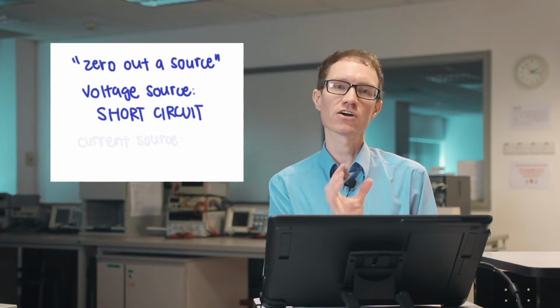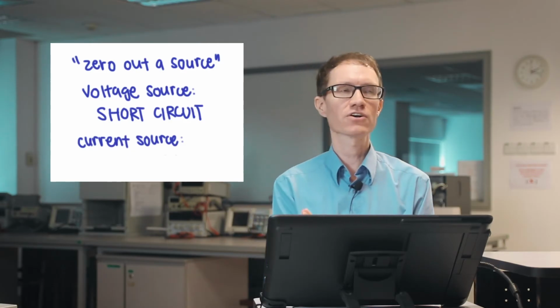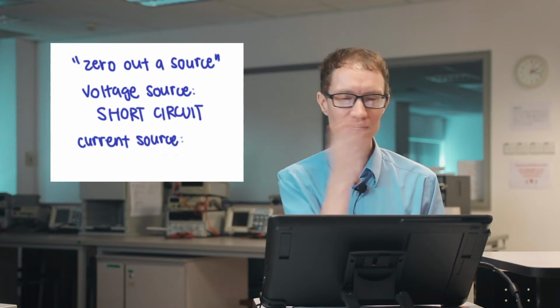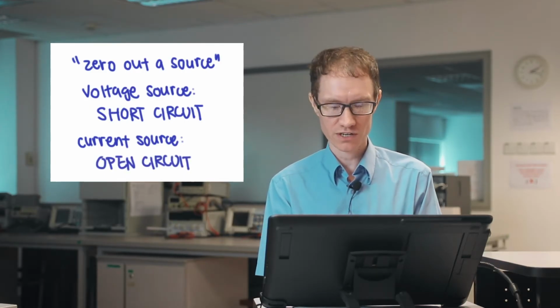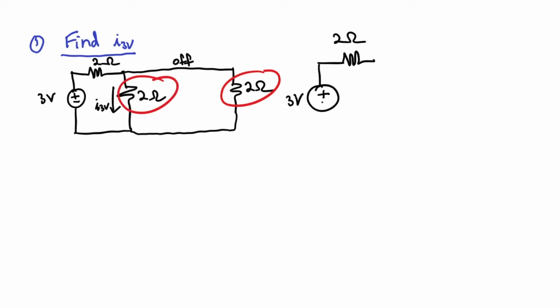Imagine that you have a current source and I say zero out the current source. What happens? Well, if a current source is set to 10 amperes and it has 10 amperes flowing through it, and I zero it down, turn the knob down, and I get to 0 amperes, then no current flows. It's like an open circuit. All right, so let's find this current due to the 3-volt source. Let me redraw the circuit here just a little bit, because we have a 2 ohm resistor, and then you could see that these 2 resistors are actually in parallel with one another.